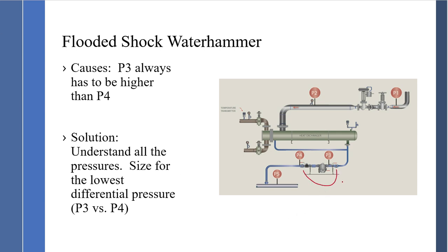The thing is, with the steam trap station, you always want to make sure that you're sized for the lowest differential across the steam trap. And there's a sizing factor that goes into steam trap sizing. So understand the sizing factor and apply it correctly. Again, have a qualified vendor support you in your efforts of sizing your steam traps correctly.